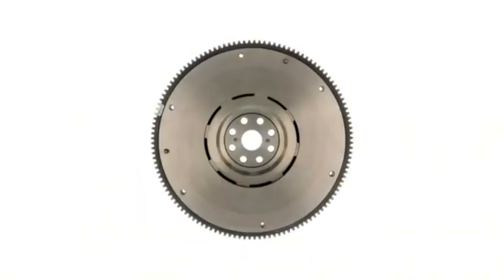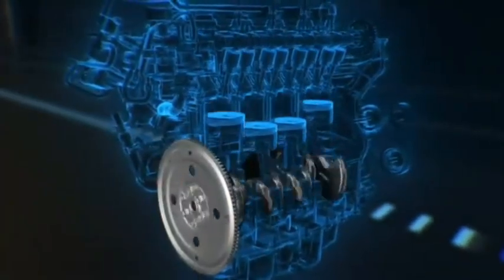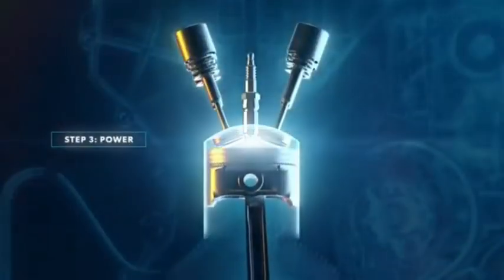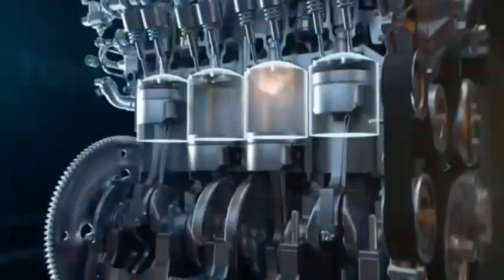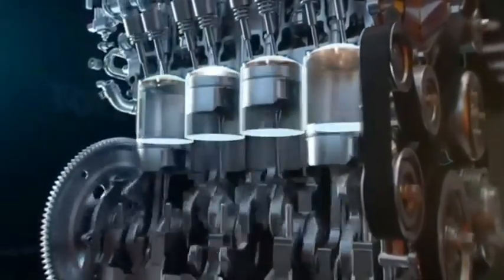The flywheel is a heavy circular metal disc attached to the rear end of the crankshaft. Its primary function is to store and smooth out the rotational energy generated by the engine during the power stroke. Since combustion happens in bursts, the flywheel helps maintain consistent engine rotation by using its mass to keep the crankshaft spinning steadily between power strokes.